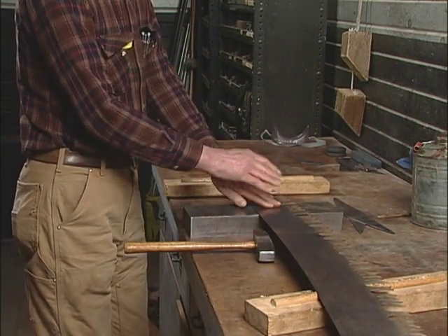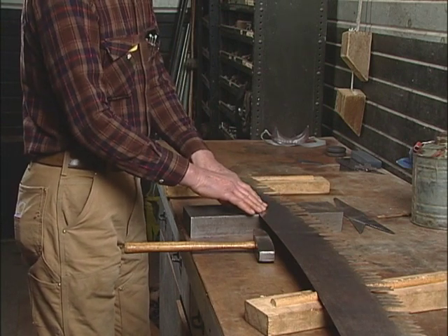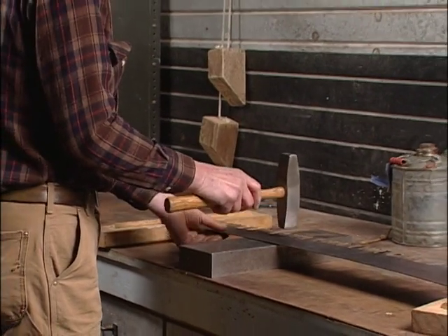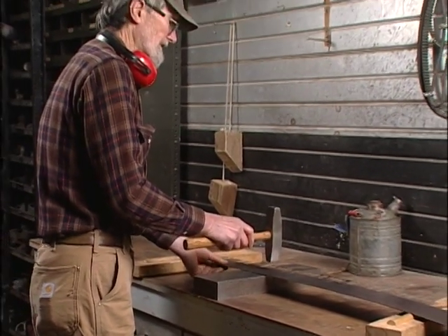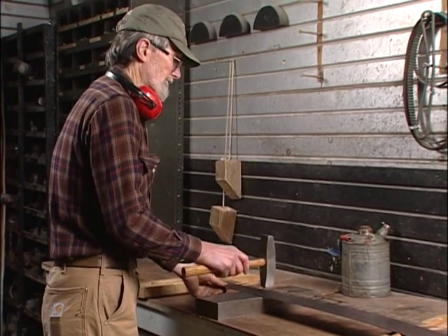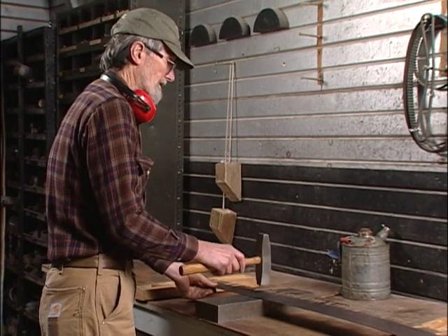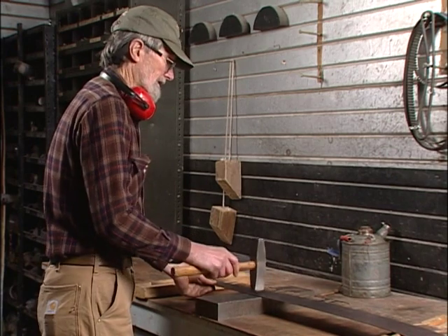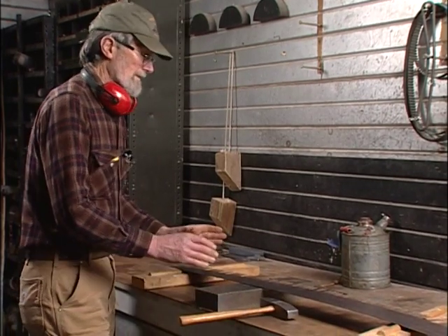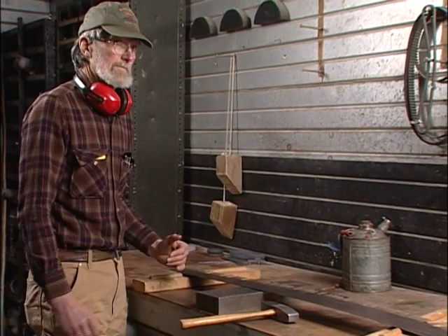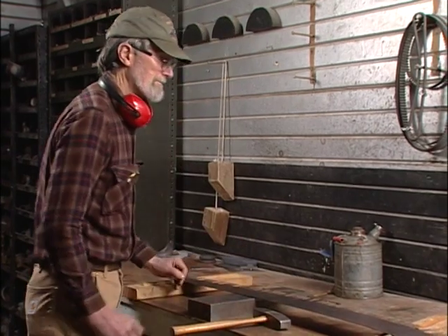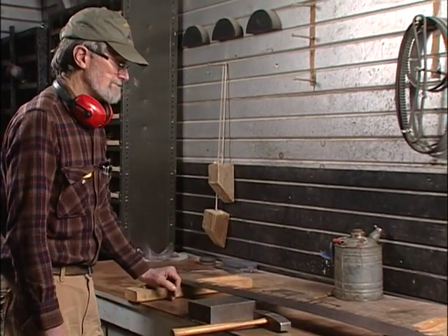say you've ascertained using the straight edges that your kink starts down here, then I'll actually start down here and take a number of light strokes. So I'll hammer, say 3 strokes, and another 3 strokes, and then move the saw a little bit, and do this sort of thing, and work up the whole saw up to the termination of the bow in the saw.